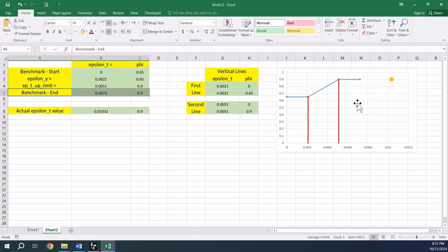When the section is tension controlled, this line will be stretched to reach this point here. But if this point is actually in the transition or in the compression controlled zones, then this line will actually try to stretch in the opposite direction. Therefore, we need to use an if statement in this case to tell Excel what to do and to always put us in the right scenario.